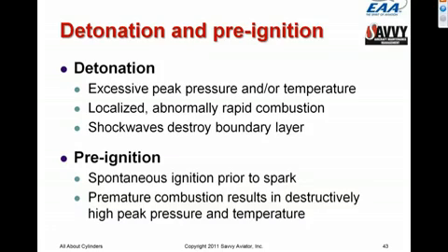And detonation is also not one of these things. A lot of people think of detonation as being a binary thing. Either it's detonating or it's not. It doesn't work that way. Detonation occurs in all sorts of degrees, from light detonation to severe detonation. And in fact, light detonation doesn't hurt a thing. All it does is tend to keep the cylinder, the combustion chamber, clean.